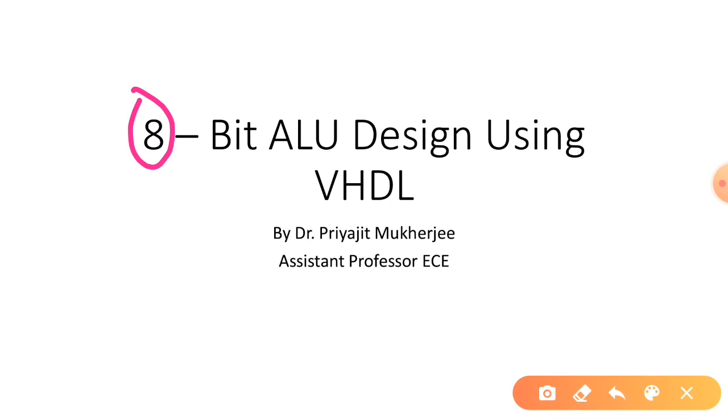When we discuss an ALU, we often call it an 8-bit ALU or 16-bit ALU or 32-bit ALU. Similarly, in case of a processor, we call it a 32-bit processor or 64-bit processor. So what do you mean by this? If we call it an 8-bit ALU, that means the maximum size of the operands is 8 bits. That means using this particular ALU, we can add a maximum of two 8-bit numbers at the same time.